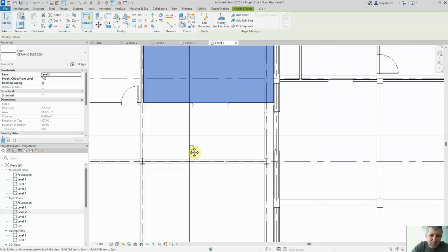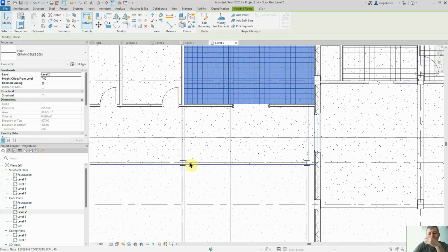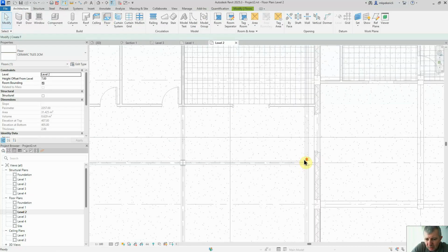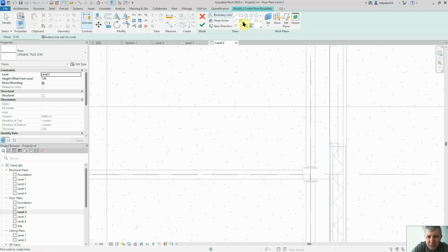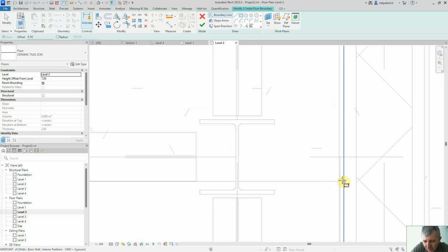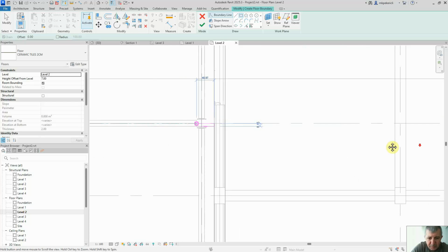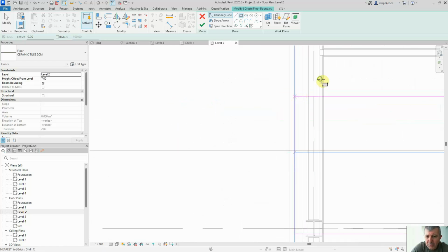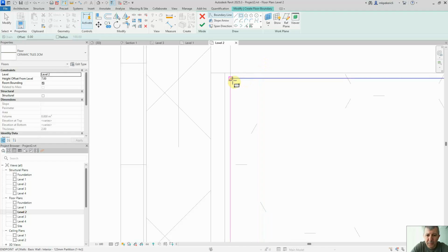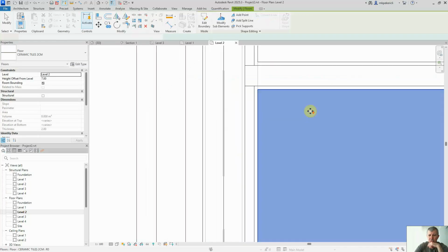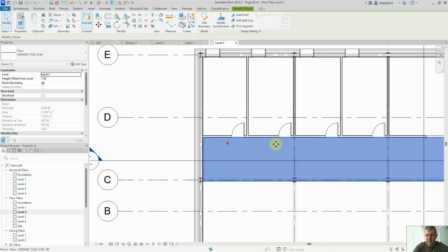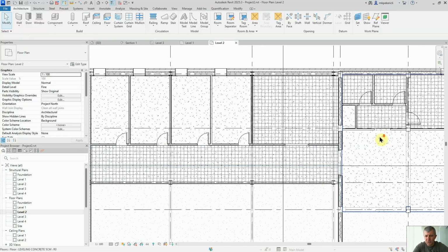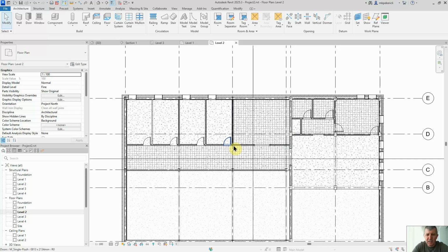Before doing that, I think I need to. Well, no, I'm going to do it anyway. I'm going to put the glazed unit in between, here, from this corner up until this corner. Yes, that should be at 7 centimeters. Perfect. So we got the wet spaces nicely clad.